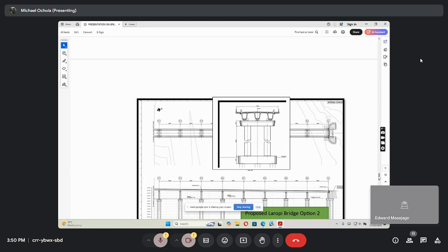You get it when your employer is doing it. But as soon as we brought in the Arup consultant to look, we said, okay, fine, look at the U-type, look at the balanced cantilever. Try to weigh the two, check and see which one is value for money and cost effective. But normally the best thing for all our designs at feasibility stage is that at least 2-3 options must be taken on, and then you assess in terms of functionality, constructability, maintenance, and environment. Then you zero in on at least one or two.